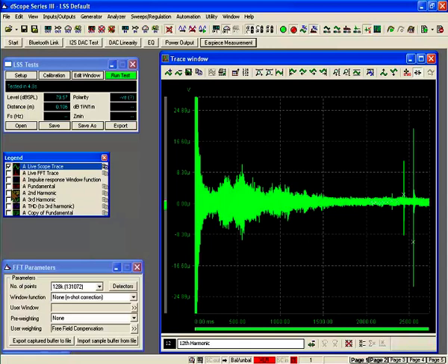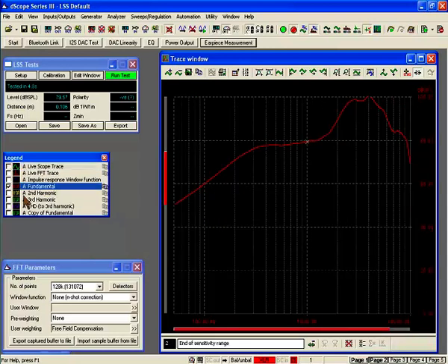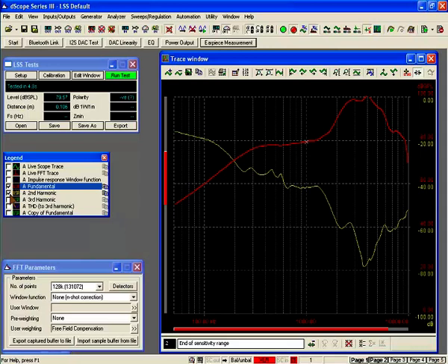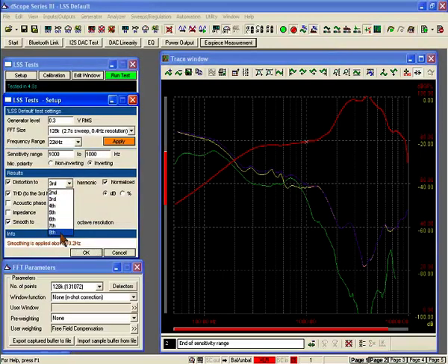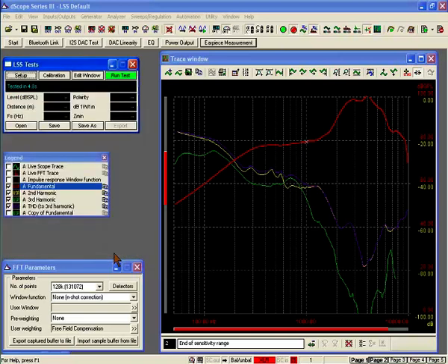So in addition to being able to measure the frequency response, or fundamental, we can also measure things like the second harmonic distortion product, the third harmonic, the THD. In fact, we can have up to the eighth harmonic, or even further if we wanted to. But in actual fact, in electroacoustic measurements, we're usually only concerned with the second and third harmonic because they tend to dominate the total harmonic distortion of these types of devices. So we have our frequency response measurement, we now have our distortion measurement, and this is our headset quantified.